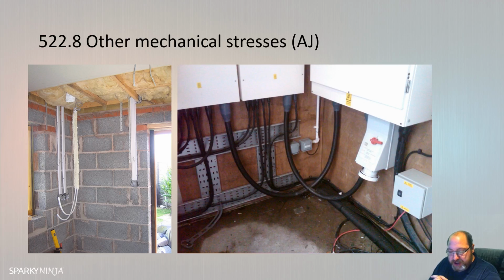Where buried in the structure, a conduit system or cable ducting system, other than a pre-wired conduit assembly, it will be completely erected between access points before any cable is drawn in. Okay, because you can have sharps or you can have bits of cable snagged. So the wiring system must be fully erected before you install any cabling into a conduit system.